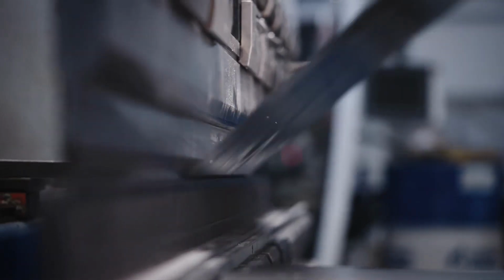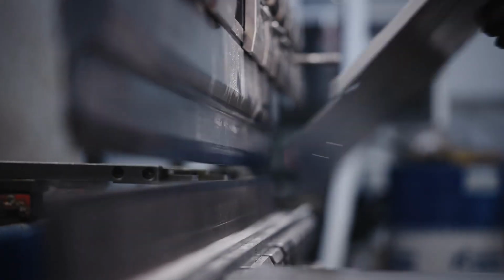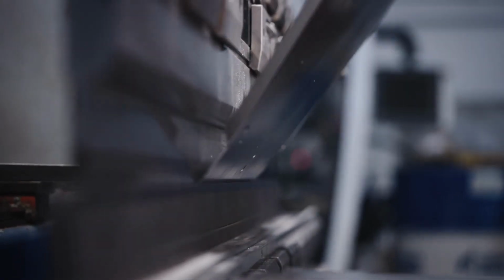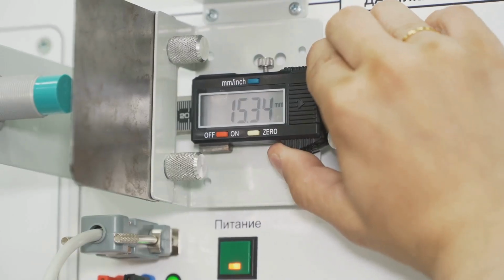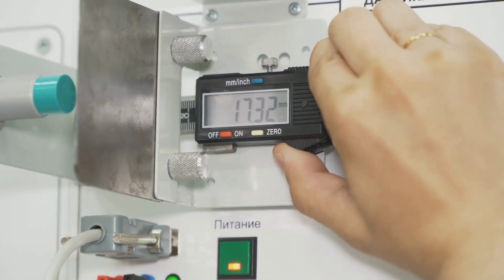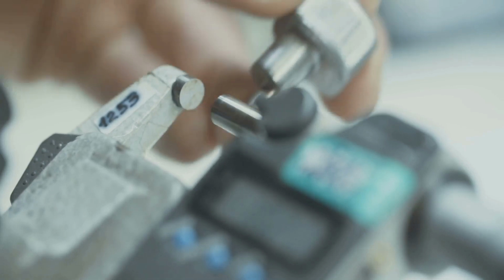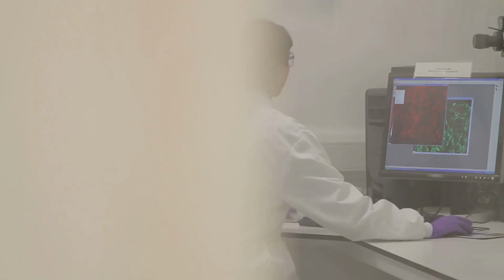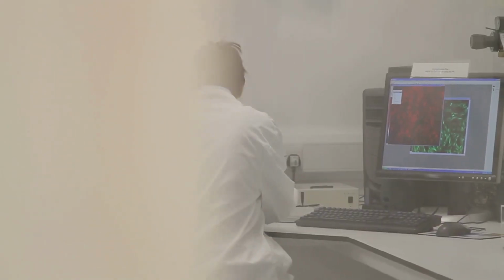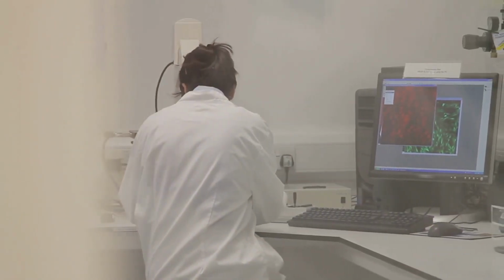This damage accumulates cycle by cycle, like tiny ripples growing into a wave, eventually leading to a crack and then ultimately to failure. It's a gradual weakening process. The εN method is unique because it directly correlates strain, the actual deformation experienced by the material locally, with the number of cycles it can endure before failing.